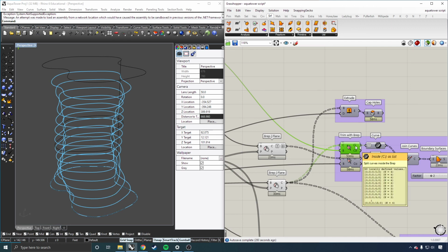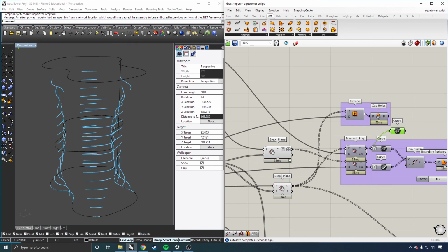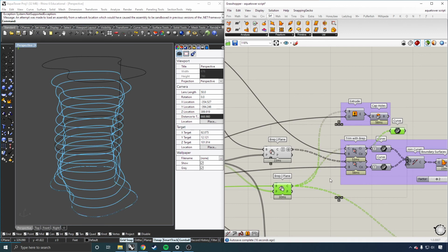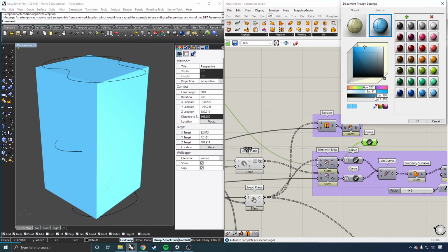And you'll notice that there is a curve inside and a curve outside. If I create a little curve tool, I can plug it into here, and you can see that it has found the curves that are inside that box. Let me change my visibility real quick. Your visibility changes for how things look in Grasshopper and Rhino are going to be here.